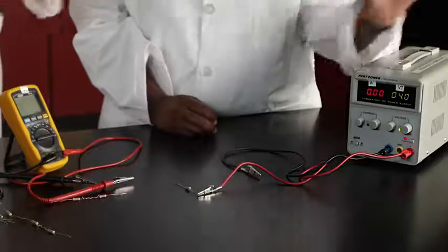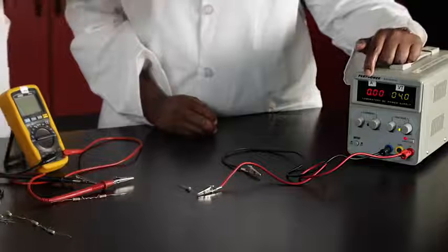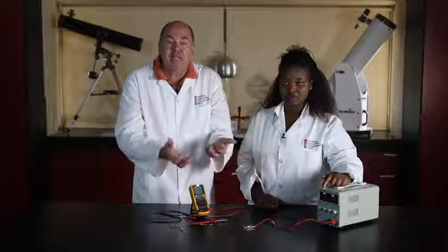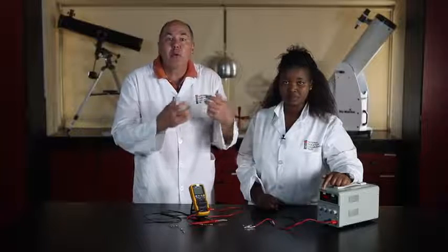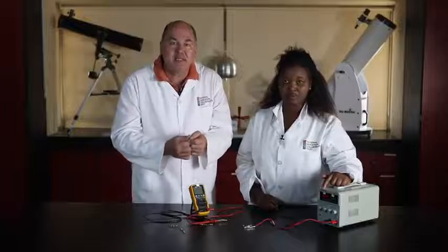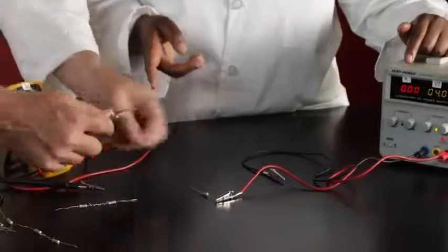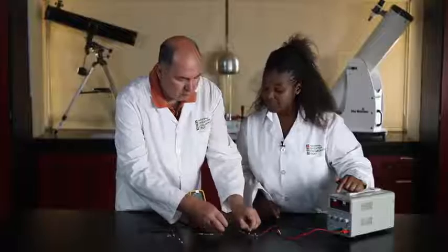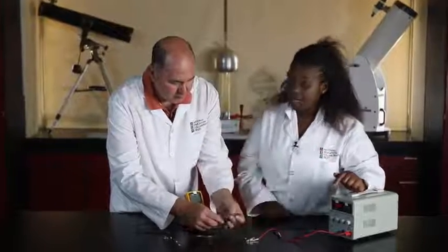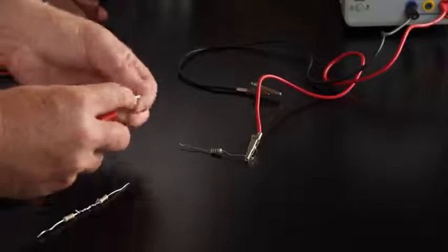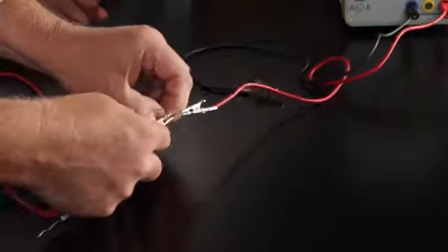And by the way, this power pack has a built-in ammeter and it measures the current passing through it. So we already have an ammeter connected in the circuit. Now we must connect the first voltmeter across the resistor. We will call this V1. It is connected across R1. And the second voltmeter is connected across the power pack.